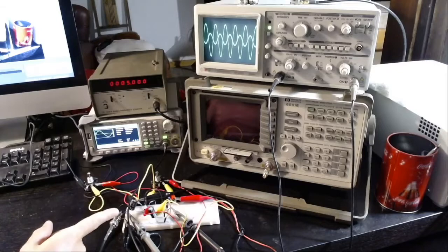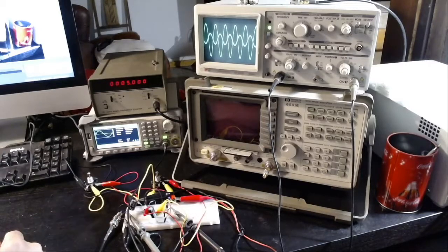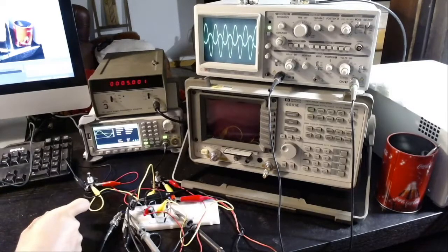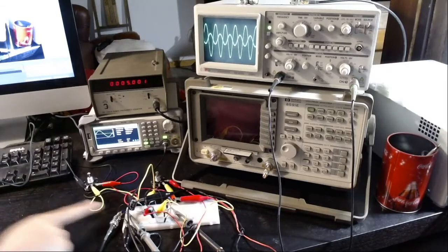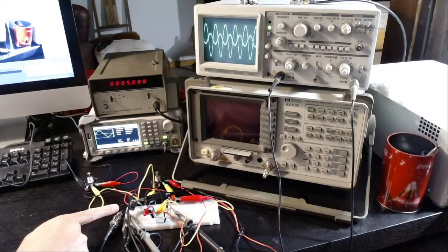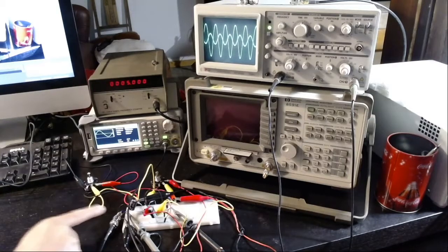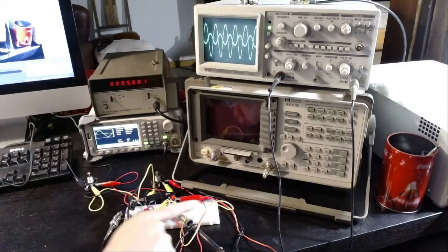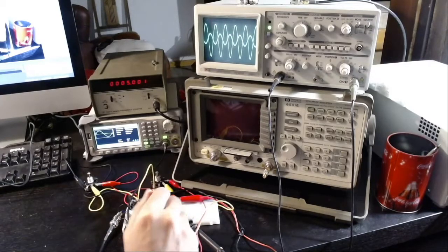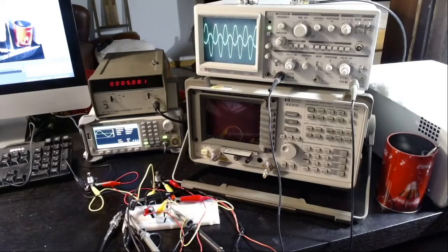This thing you see here is the amplifier, which I've been using in my previous videos to amplify the signal coming from a mixer. So the signal was going to the input of the amplifier, and it contains frequencies from very low frequencies, basically 0 to 500 megahertz. And the goal of this amplifier is to amplify only the low frequencies, ideally from 0 to 20 kilohertz, which is the audible voice.